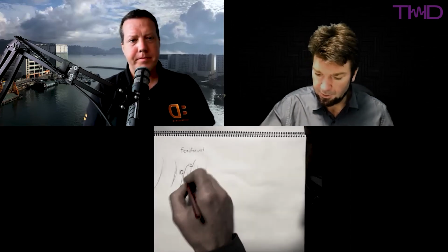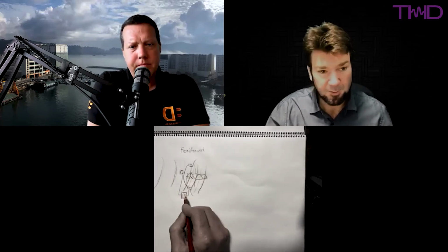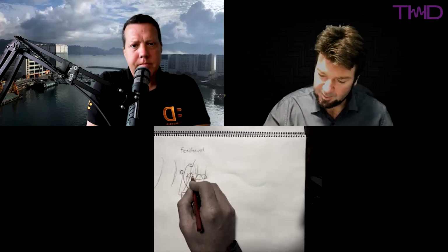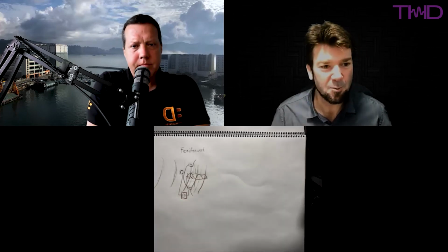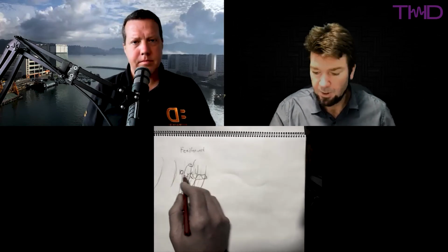And then you just have to calculate what I should do with this microphone signal so that when I put it out of the speaker, it ends up as a cancelled sound wave at the eardrum. There's a direct calculation for that in feed-forward, and then you can work out what the filter is going to do. When I get a signal from the microphone, what should I put out of the speaker so that the sound wave from the outside reaching the eardrum and the sound wave from the speaker reaching the eardrum are exactly opposite? Now, you just said people with different ears and so on, does it make a difference?